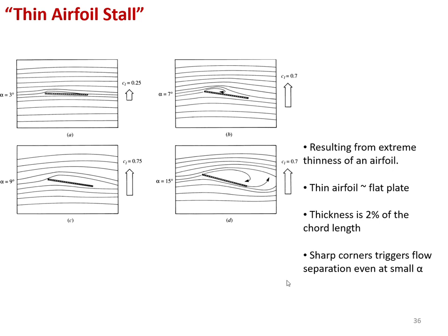But the difference between a thin airfoil stall and the leading edge stall is the fact that thin airfoil stall happens at a much faster rate, and because they usually have a lower camber, their maximum lift coefficient is not going to be as high as the regular non-thin airfoil.